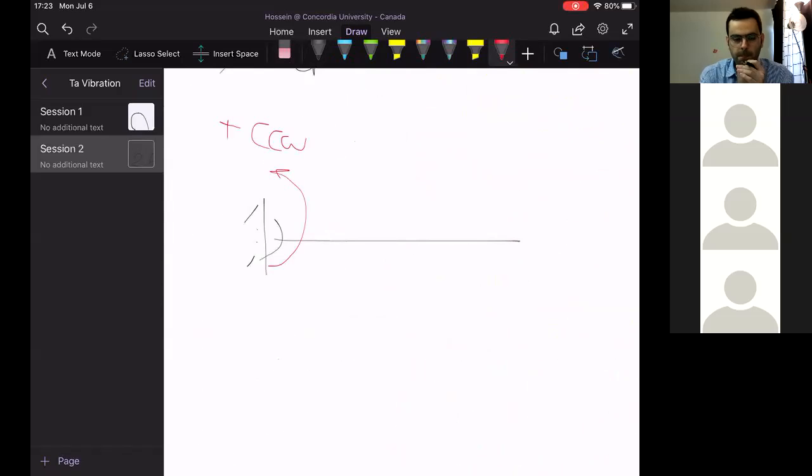Once we determine the positive direction, the second step is disturbing, oscillating, and moving the system a little bit in order to find what kind of forces will oppose the motion. Since we consider the positive direction to be counterclockwise, it is simpler and easier to just rotate the system in the assumed direction.